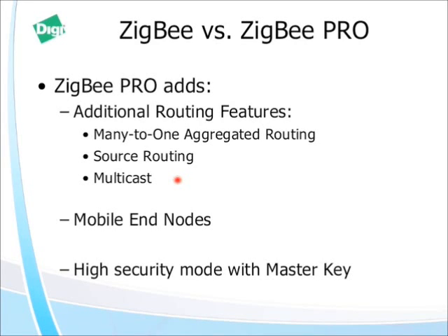Network, and you have a light switch, and it's controlling a bank of lights. If you're just doing a unicast transmission where you're starting at the first light and you're terminating at the last light, and I turn off the switch, you're going to see kind of this ripple effect of all the lights going off one after another. That's not a very pleasing thing. What you really want is a multicast where everything receives the message at more or less the same time and shuts off at the same time. That's what a multicast transmission allows for.